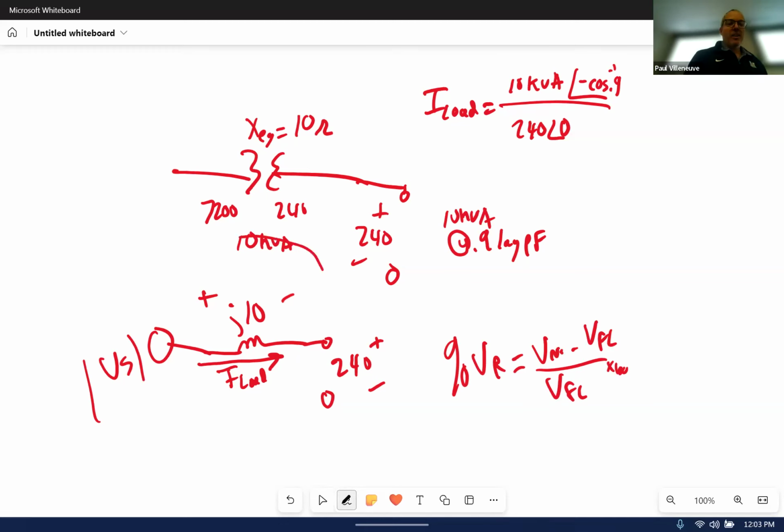But literally all I'm trying to do is get the equivalent voltage drop across the transformer. So if I just said, what is the voltage drop across the transformer? You're done right here. Once you have this step, you're done. Voltage regulation would just be the next step to include that. And remember, your percent voltage regulation is a percent and it's magnitudes only. Don't include any angles. If you give me a percent voltage regulation of 3.2 at an angle of 25%, probably not going to get full credit. Okay.